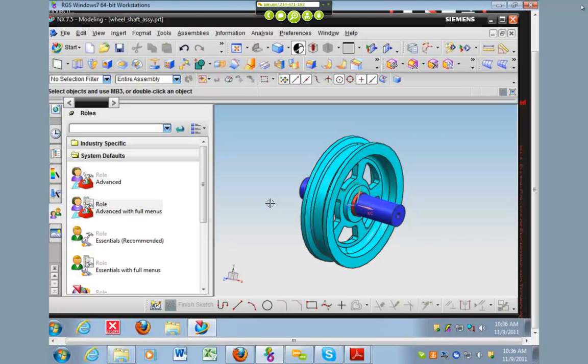The surface-to-surface one really only works if you have a shared surface between the two meshes. It requires you to have all your nodes line up, just like in HyperMesh. Some of you probably had the problem where your parts flew away because the two meshes weren't perfectly connected. You'll have the same problem in NX if the two parts' meshes aren't connected.